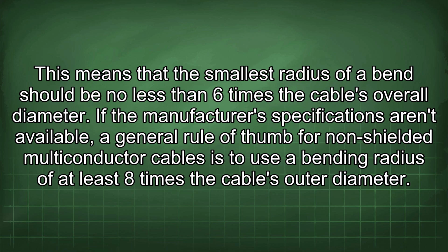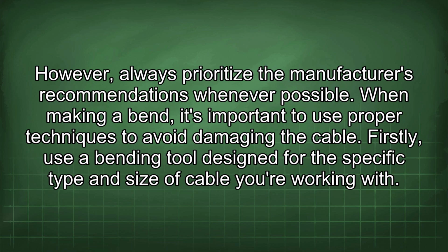If the manufacturer's specifications aren't available, a general rule of thumb for non-shielded multiconductor cables is to use a bending radius of at least 8 times the cable's outer diameter. However, always prioritize the manufacturer's recommendations whenever possible.